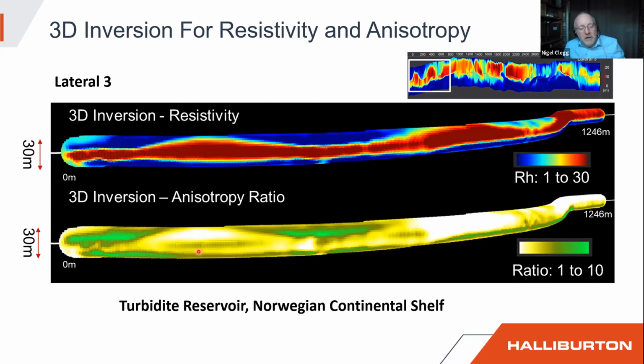Now, it's interesting that this was run for a paper to create some nice pictures, and the thin shale layer at the bottom at the initial parts of this investigation was an annoyance. I ran the inversion to create pictures of the resistivity, but then I noticed that it was telling me that the unit below was anisotropic. I was expecting it to be water-filled sand.